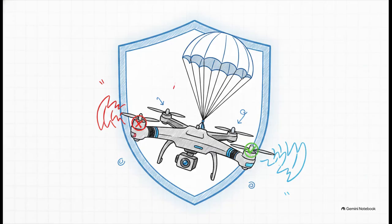But listen, true autonomy absolutely requires fault-tolerant control. Commercial drones need a real-time safety net to combat calculation latency, communication delays, and just sudden random hardware deaths. The key here is redundancy. By carrying dual GPS modules or multiple internal measurement units, the flight controller can actively compare the incoming data. If one sensor suddenly dies or starts spitting out crazy numbers, the drone immediately detects the failure, completely ignores the bad sensor, and switches to a backup, or it triggers an emergency safe descent. It is a vital layer of self-preservation.